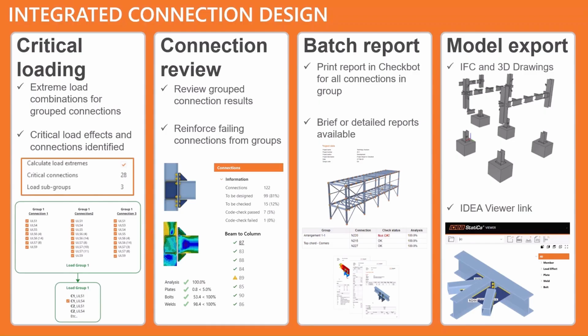Now, this will basically complete your workflow for you to be able to design your connections a lot faster. But the last part here on the right-hand side is one way in which you can take it to another level. So here, let's say you are working with some detailers. You have the option of exporting the connection as an IFC file, which can then be read by multiple other detailing software such as SDS2, Tekla, and Revit.